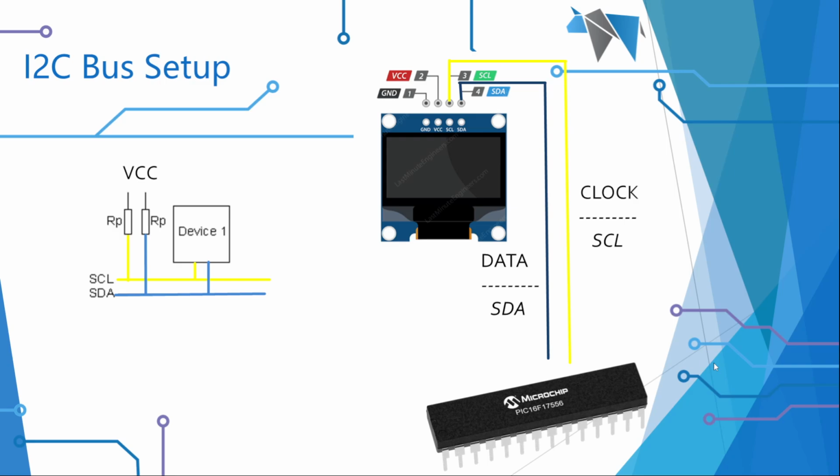Because the I2C bus, I use it interchangeably. This bus needs to be pulled up high. It needs to be pulled north. So that's what in my brain, that's why I say pull north. So I have my VCC, whatever voltage that is. Remember, on these devices, they say VCC, VDD, interchangeable. 5 volts, whatever voltage it is, you need to pull them up with these resistors here.